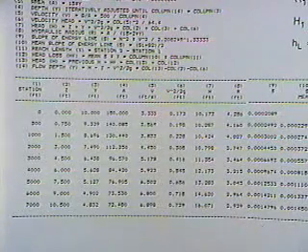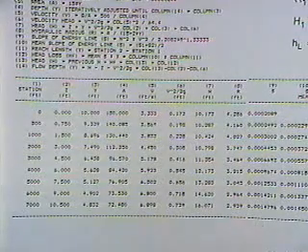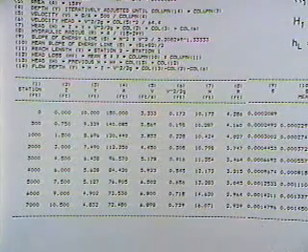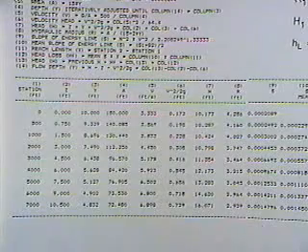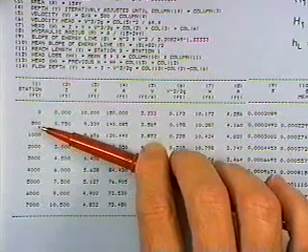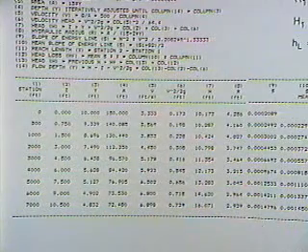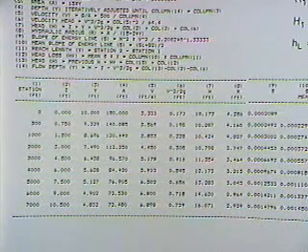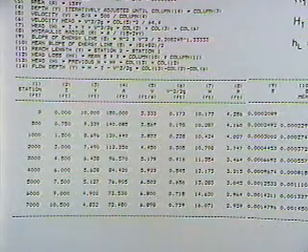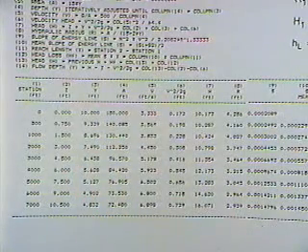And so what we're doing, using the same geometry as before, though this method does not limit itself to that simple prismatic channel. It could be a highly irregular natural river that we're working with, just as pertinent. And so what we do here, we set the stations. That's the difference. The different cross-sectional locations are set at the beginning, and we've got to know a starting condition. And we know that from the problem statement. The river into which the channel is flowing is at a depth of 10 feet. So given the 10-foot starting elevation, we can run through the computations.